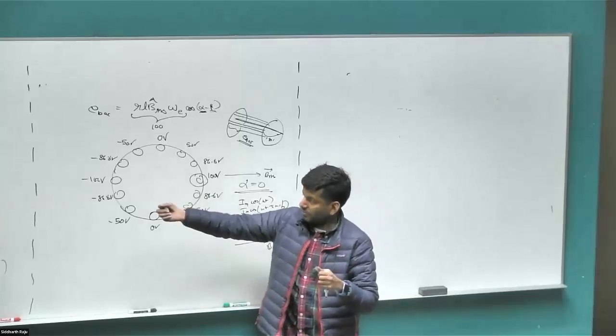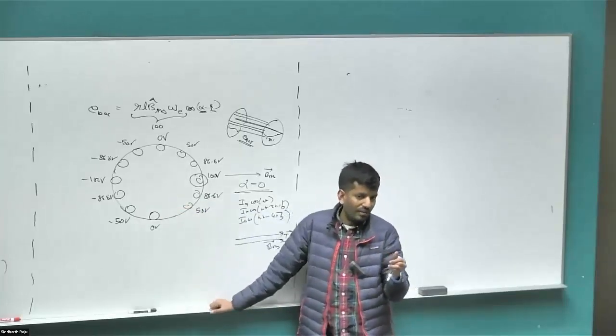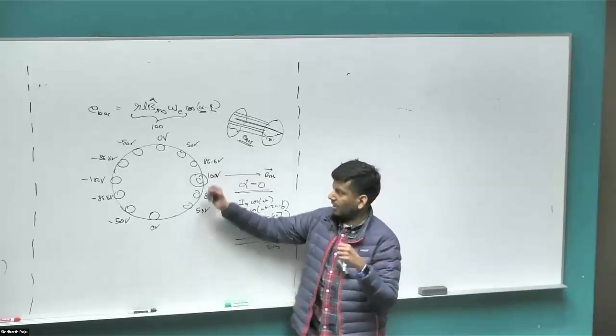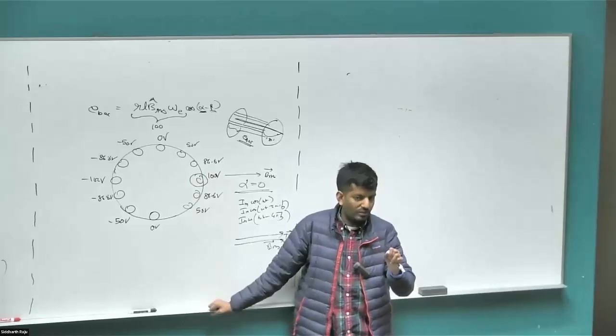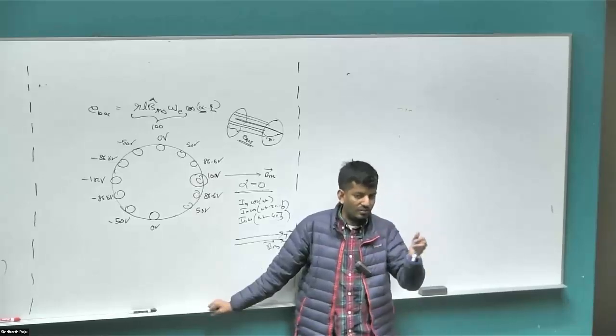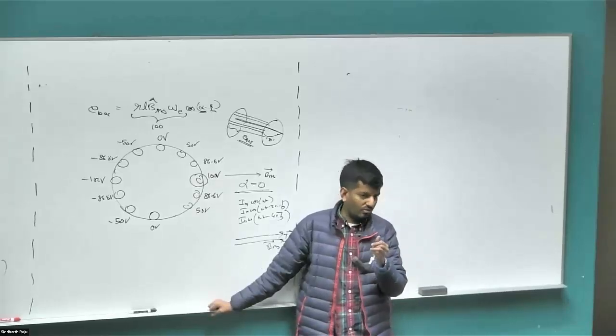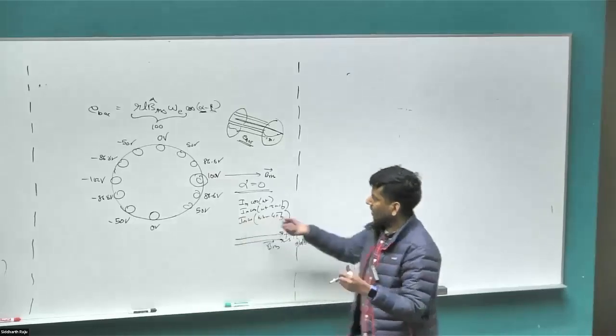It is just that the way our B field is sinusoidally distributed, it induces a voltage on the rotor bars which are sinusoidally distributed. So without putting any additional effort into creating the rotor structure with a different set of windings and everything, we have created a sinusoidal distribution. Right? So let's consider another angle.